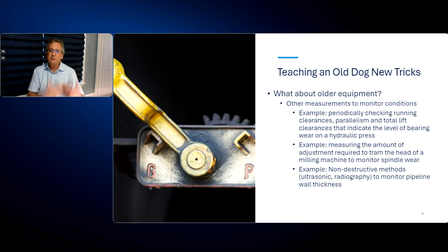And again, a maintenance person could check this at some frequency, maybe an operator if it's easy to do. That's what we'll get into in two weeks, operator assisted maintenance. But whoever does it, we have to be clear on what's acceptable versus not acceptable and have some limits. And say, okay, if it goes beyond this, we've got some significant bearing wear that we need to address, and we'll go schedule that with maintenance at a convenient time.